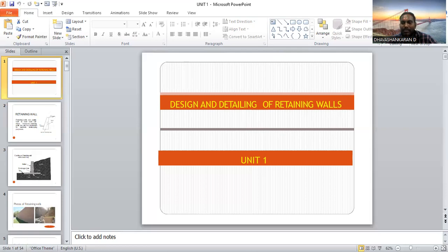There must be some safe bearing capacity. We know that the safe bearing capacity of the soil will be known. We can test it based on the safe bearing capacity. Then this is the check against overturning. When this pressure is exerted on the side of the soil, the wall will overturn. Then this one is sliding, the movement of the wall, that is called sliding. So how to resist the wall from sliding, which is caused by the horizontal force. Then all these factors will be enlisted.